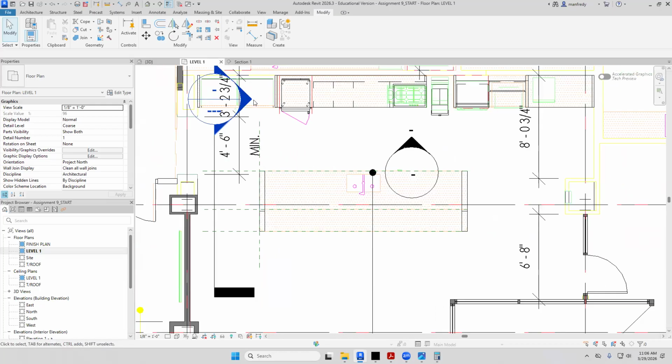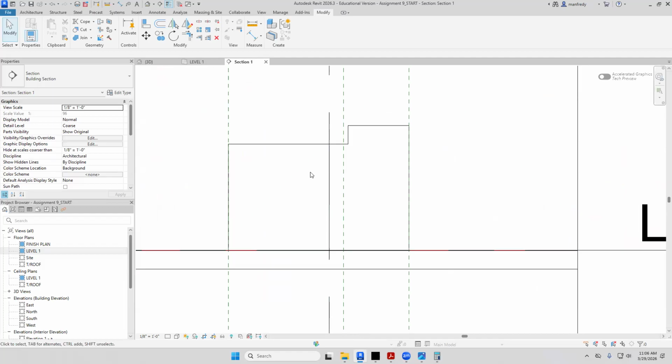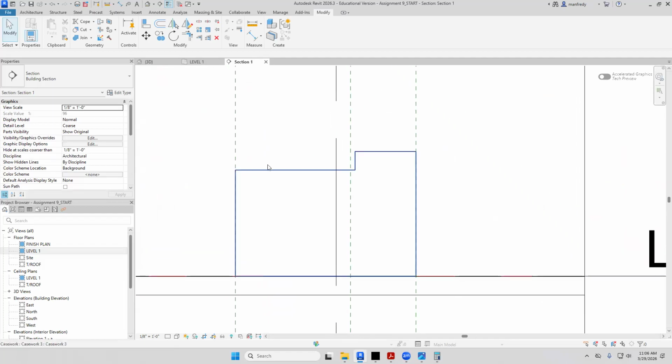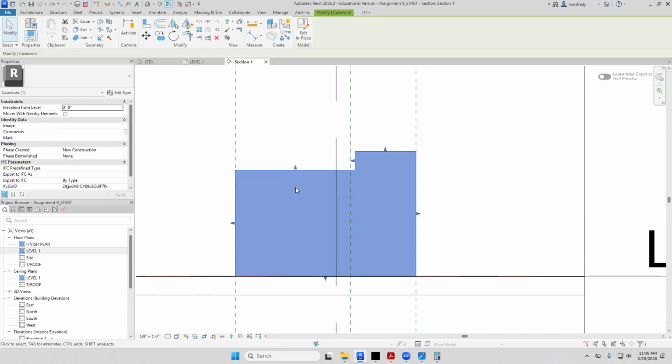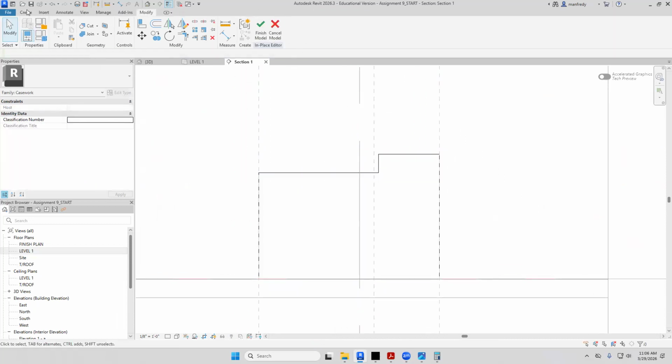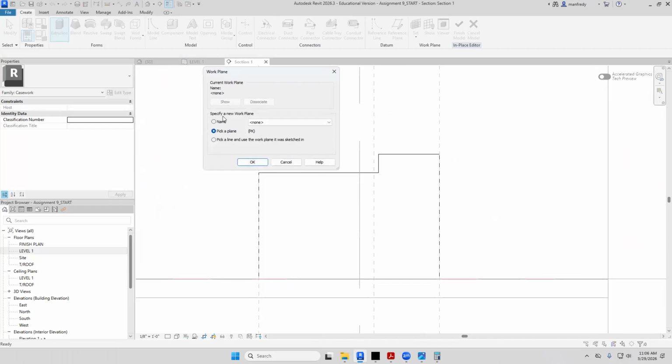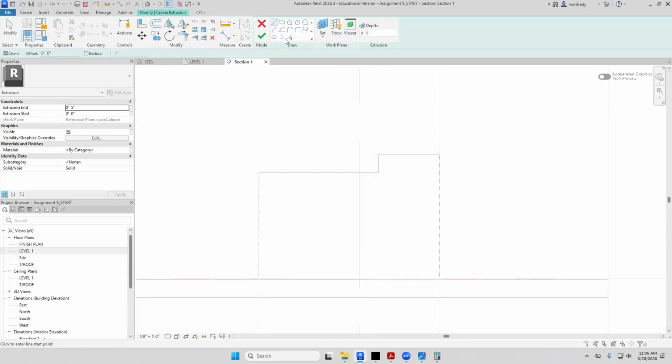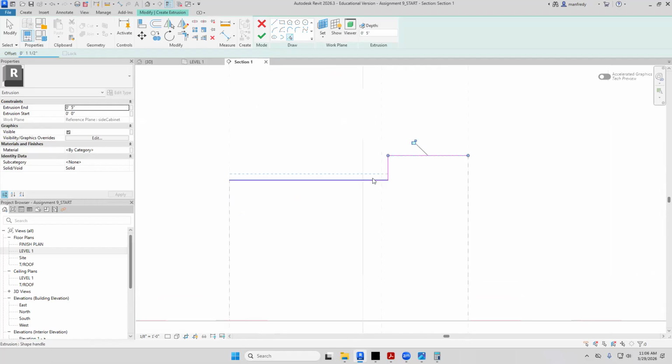So I just drew that wall, add the side view. This is the section. And then I can actually use this view to draw the countertop as well. I can go back into this model and build another model on top of it. That's the countertop. So they're all together. So I go back, edit in place, and here I go to create a brand new extrusion. I can tell it to talk to that plane again. And here I can just simply choose the top of this and then make it 1.5 inches away from whatever I touch. And this is the thickness of the countertop.